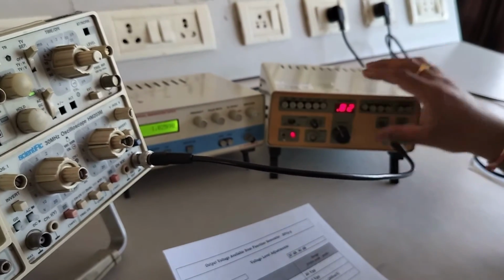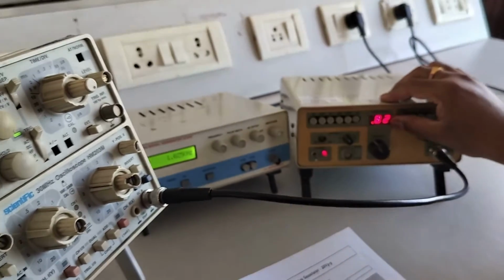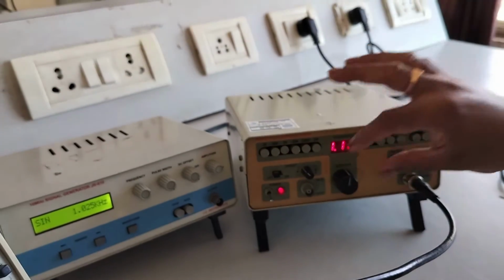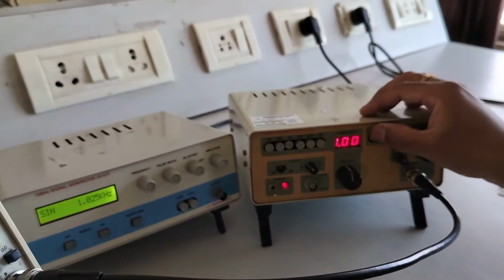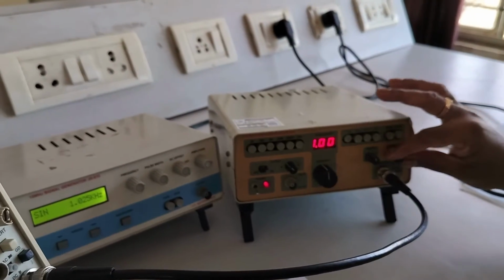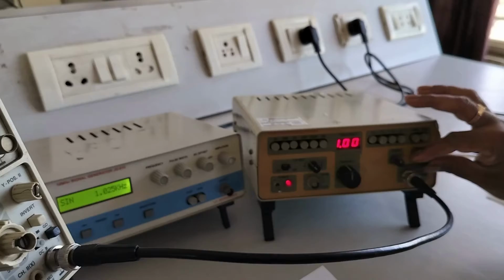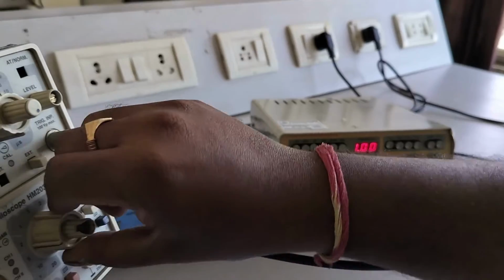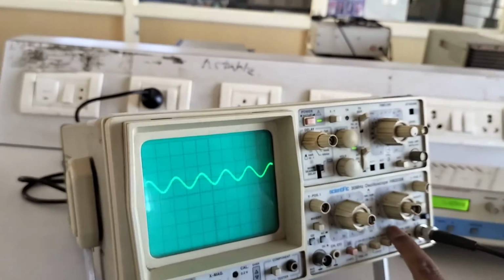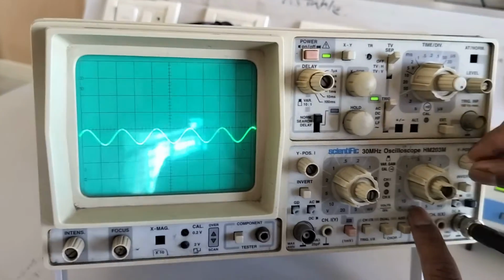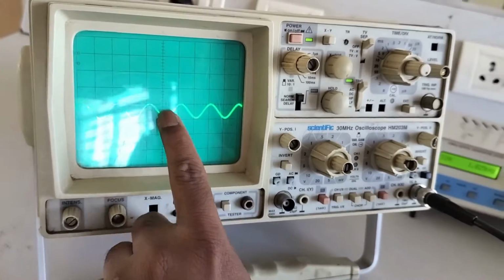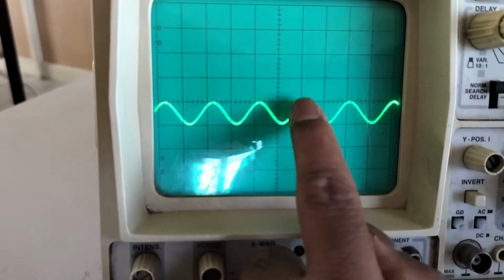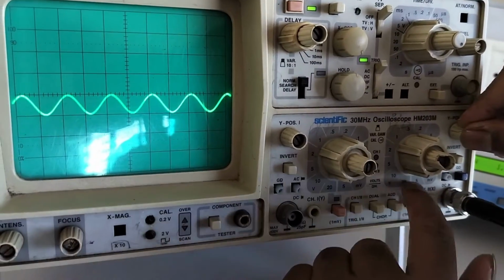First, this is the frequency readout, an LED display, and these are the selections. First I will keep the frequency at 1 kHz by adjusting here, and I have taken a sine wave, and I am keeping both buttons in release condition. I will show you the maximum voltage. I have kept this fully clockwise in release condition. The voltage will be 20 volts peak to peak. See here, on the CRO it is at 20, and the sine wave you are getting covers one division vertically. As you measure the voltage across the vertical axis, one division is 20, so 1 into 20 is 20 volts, that is what we are getting.